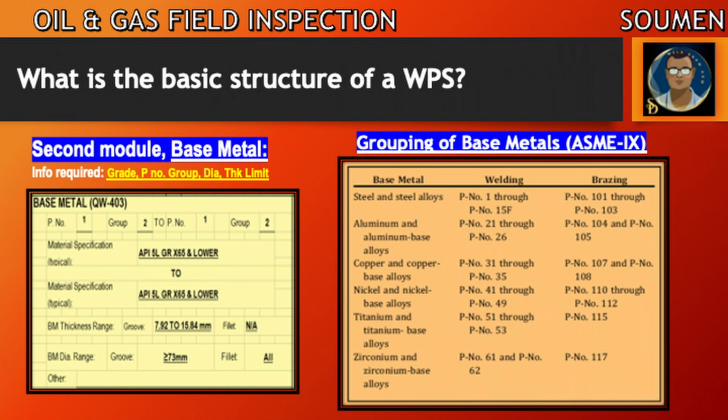Why is it restricted to 73 mm? Because for less than 73 mm, in company standard, it is not allowed to weld with SMAW welding. You must weld it through argon route. That's why SMAW groove welds are restricted to 73 mm and above. For any WPS, if the test coupon is a butt weld, then fillet will be automatically qualified.